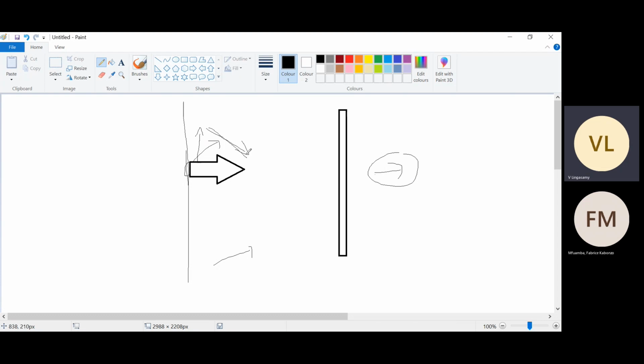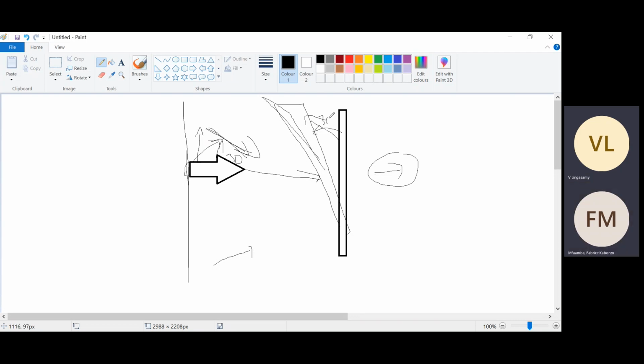So we want, for example, this reflectarray to be focusing like this, right? It's 30-degree, correct. So instead, what we can do is move this reflector in this direction, in this fashion. You can see here it remains pointing towards like this. So instead of rotating the horn by, for example, 30-degree, we are going to rotate this reflector by 30-degree. Then it will become like this, right?